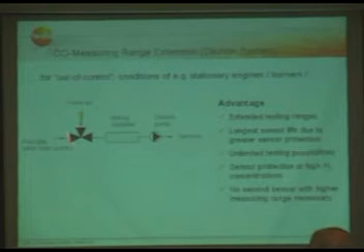But if you're using the dilution system and you dilute with factor 20 or 40, the sensor gets only a very small concentration of the real CO, and therefore you can expand the measuring duration, and of course the lifetime of the sensor.